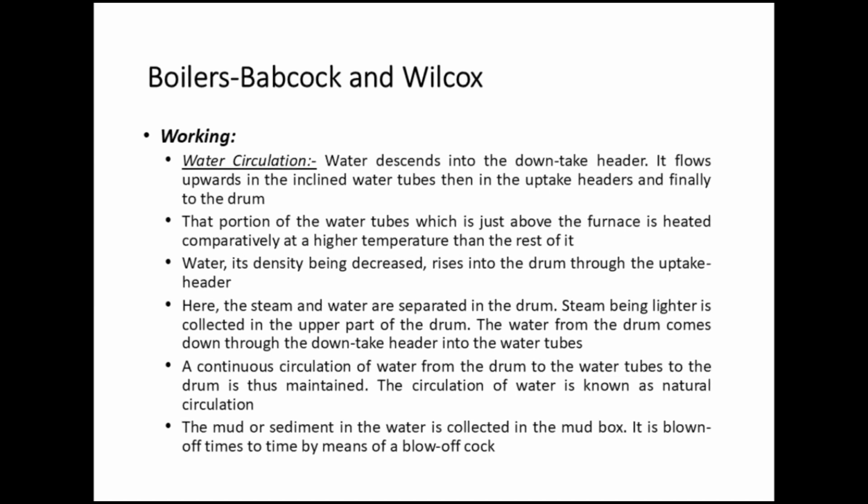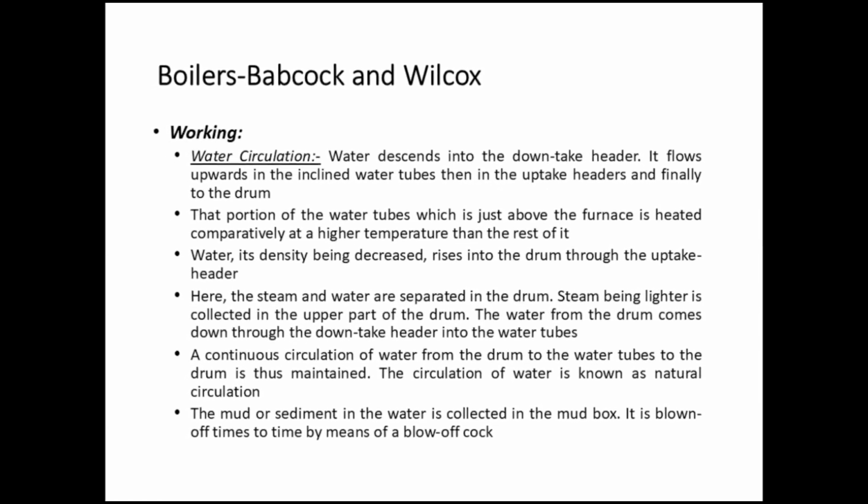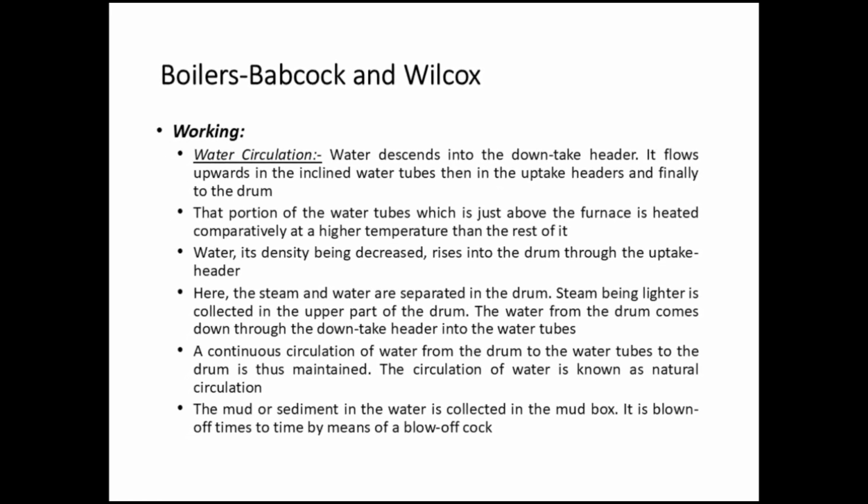Boilers. Babcock and Wilcox. Working. Water circulation. Water descends into the downtake header. It flows upwards in the inclined water tubes, then in the uptake headers, and finally to the drum. That portion of the water tubes which is just above the furnace is heated to a comparatively higher temperature than the rest of it. Water, its density being decreased, rises into the drum through the uptake header.